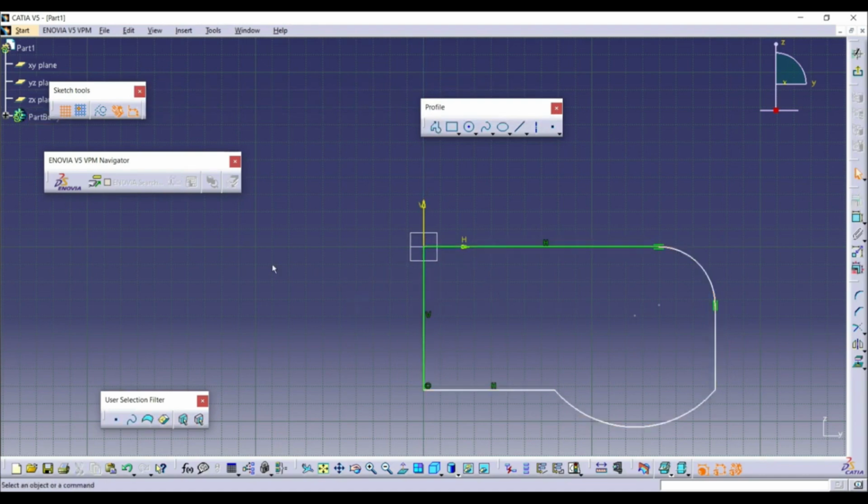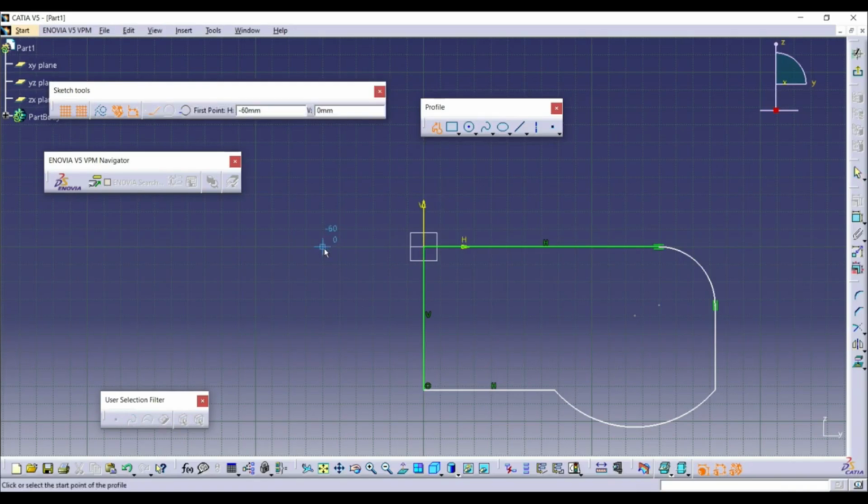Now let's go here to the sketch tools. Here we have a grid. But also here next to the grid, we have a snap to point. So let's turn on this one. Let's select here profile. And now as you move your mouse, you can see that you can only position your mouse at the cross sections of those lines. As you can see, for example, here.